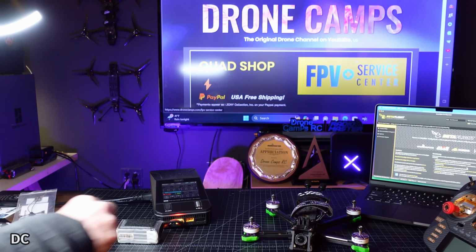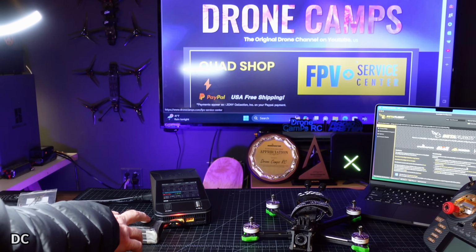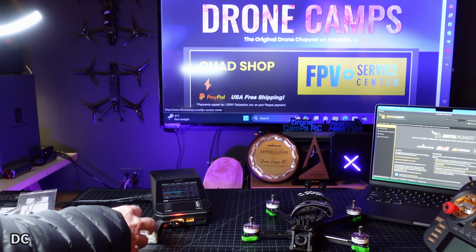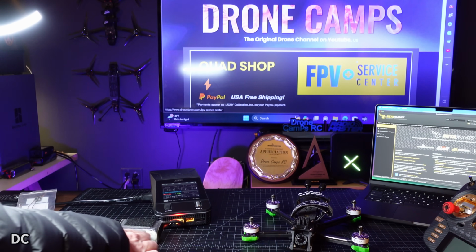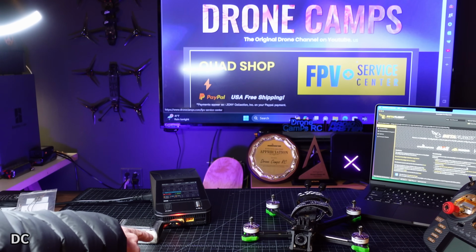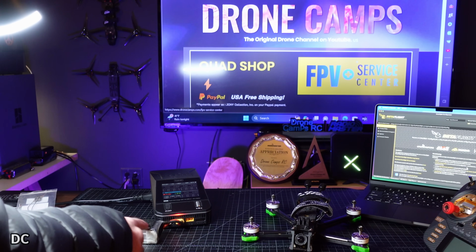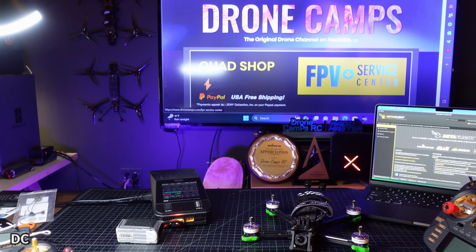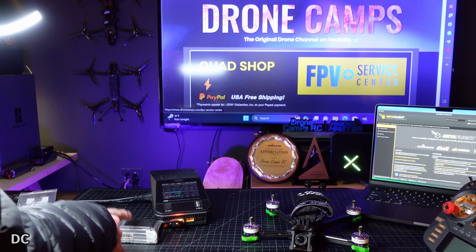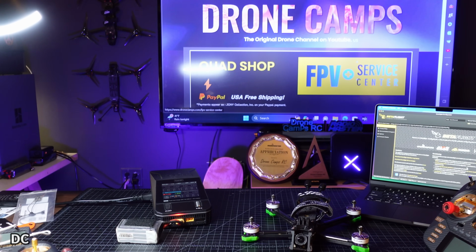If you have a hot LiPo on a charger, it means that that battery is on its way to probably igniting at some point. Now, the other thing you can look out for when you're charging a LiPo: if you breach one of these cells, if one of these cells pops at any time, that means it got so hot, it sprung a leak somewhere, and once air hits these, fire is next. So sometimes you have about 15 to 30 seconds to get this outside before it ignites. I have literally carried these in my hand and thrown them out the front door and had them explode on the ground in front of me.